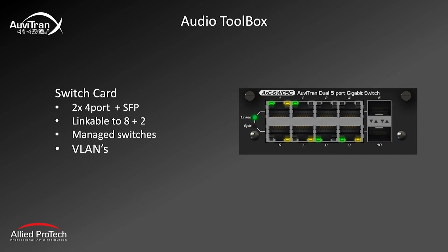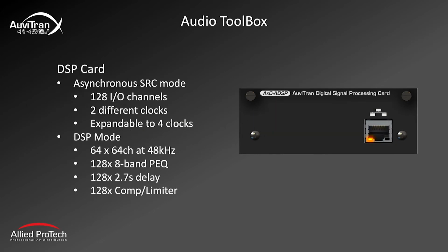You can link these together to give you a 10 port or an 8 RJ45 plus 2 SFP switch, or keep them separate, maybe for primary and secondary. These are also managed switches, so you can add VLANs and so on as required. In addition to all this I/O, we also have a DSP card, which we can use in 2 different ways,